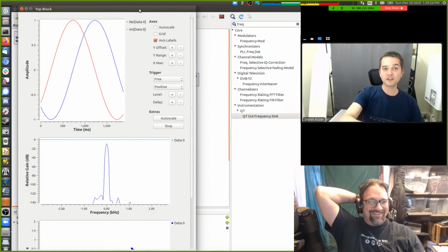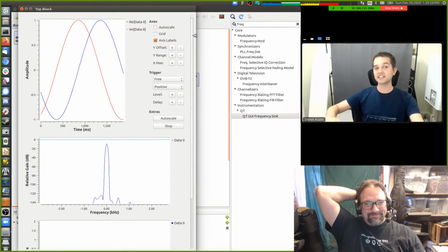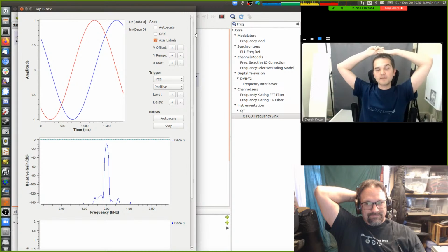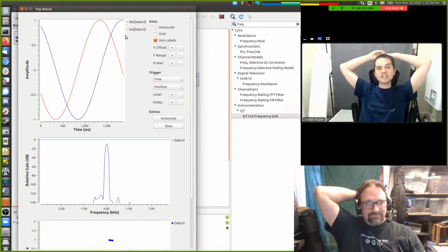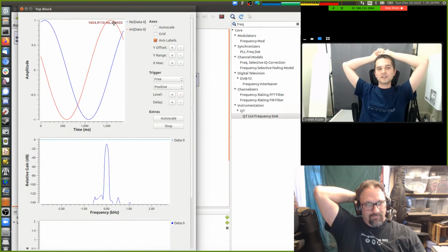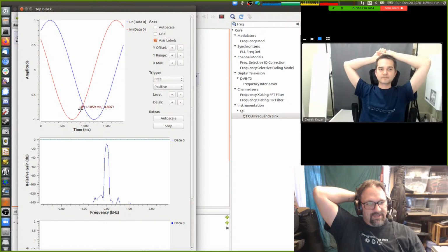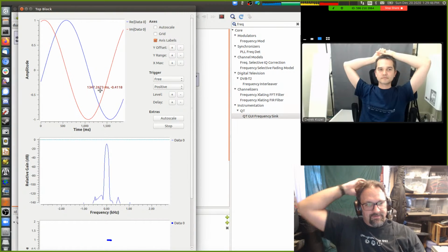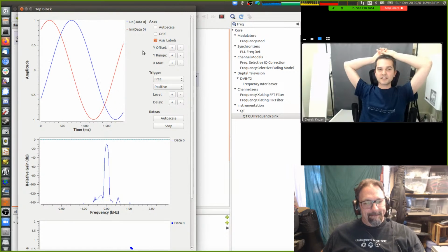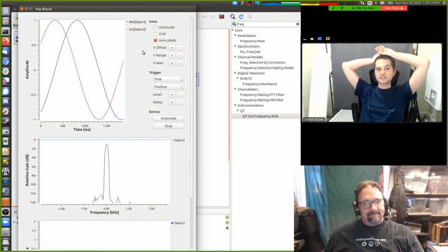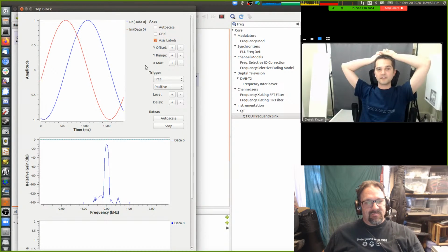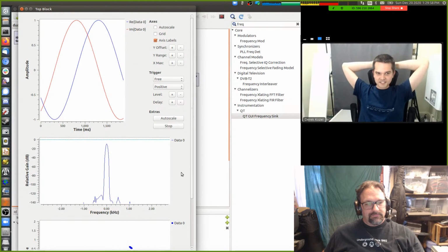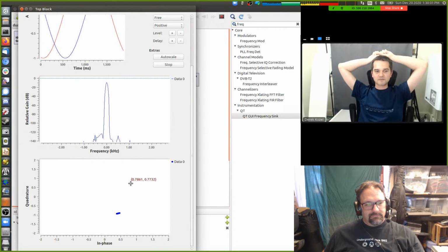And so the cool thing, let's pay attention to one thing. Does it look like the imaginary, the quadrature component, is leading or lagging the real signal? In this case, it looks like the imaginary is lagging, because the real signal is in front, so the imaginary is behind it. Okay. So it is negative 90 degrees from the real component. Yes. So now let's scroll down and try and dig into what on earth this rotating blob is.